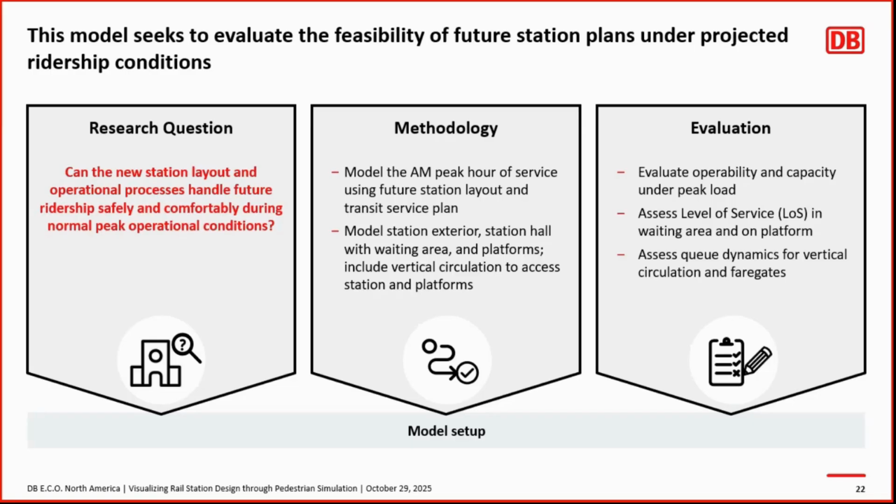Similar research question, can the station handle projected ridership? For this model, we wanted to just look at average AM peak hour projections. So not looking at an extreme scenario, looking at a more normal scenario. And we wanted to evaluate level of service, queue dynamics for vertical circulation, as well as for fare gates.